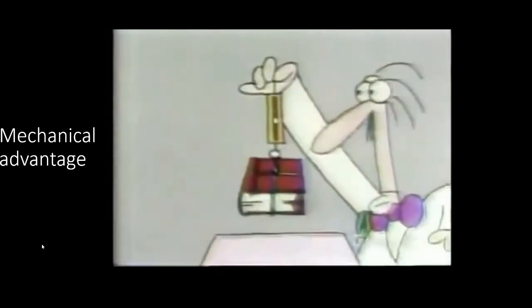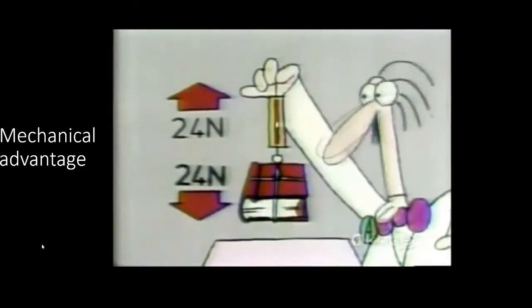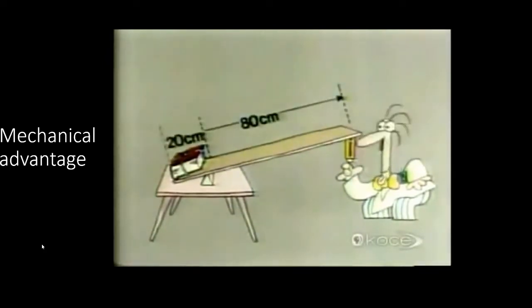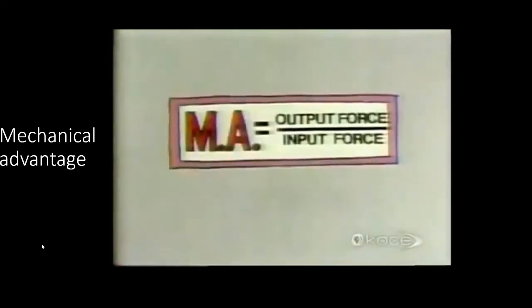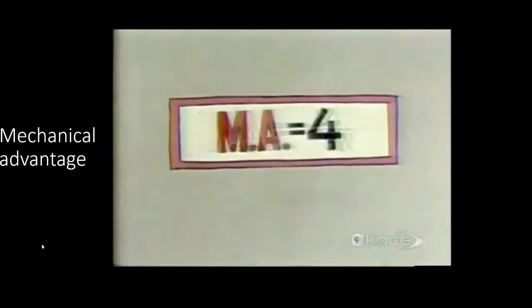Professor A lifted it straight up, so he had to pull against the full force of gravity, which was pulling the book down. But since Professor B's lever arm was 4 times as long as the arm the book was resting on, he only had to pull with 1/4 the amount of force, 6 newtons instead of 24. In other words, his input force was 6, and his output force was 24. And all you do to calculate the mechanical advantage of a machine is divide the output force by the input force. So Professor B's lever had a mechanical advantage of 4.